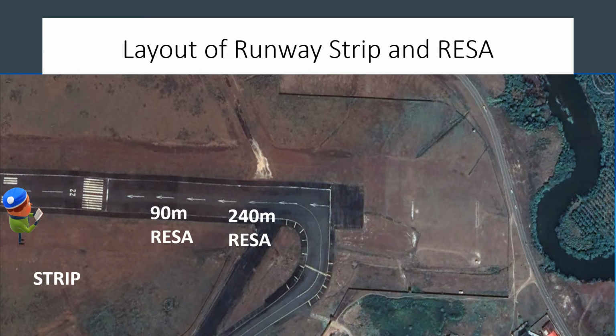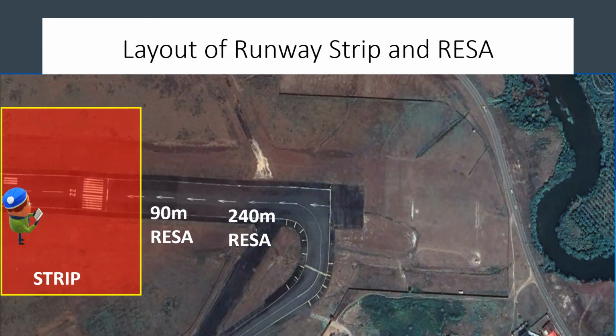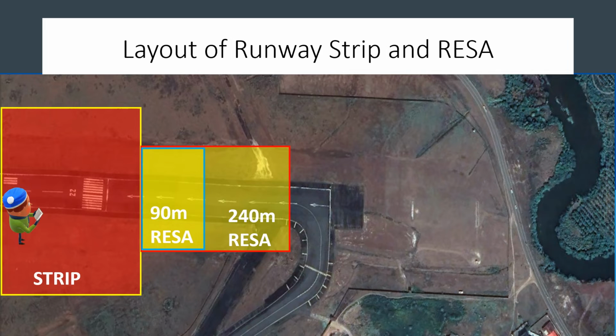Let's quickly look at a field view of the runway strip and the RESA comparatively. Currently you can see me standing along the side of the runway. I am positioned in the strip of the runway. Beyond the strip, I can see the 90-meter RESA, if that is what is provided, or the 240-meter RESA, if that is what I have. So beyond the strip, you have your RESA, and you measure your RESA accordingly based on what you have.